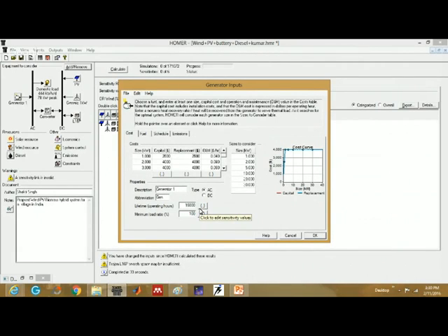So what will happen if you don't consider the minimum load ratio, 30% or whatever the value is? What will happen now? See, in the case of a generator, the complexity of the system increases, because the lifetime of a generator is in operating hours, not years, right? Generator lifetime is 15,000 operating hours.